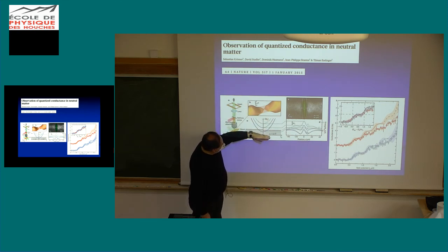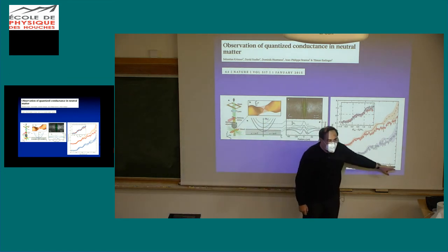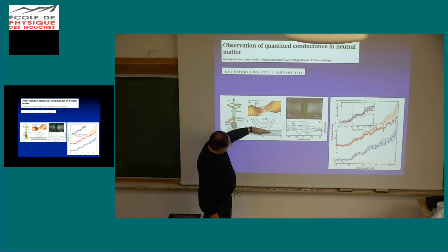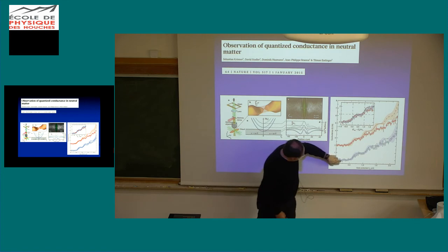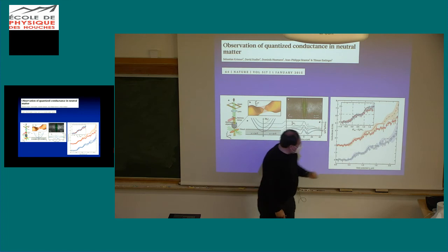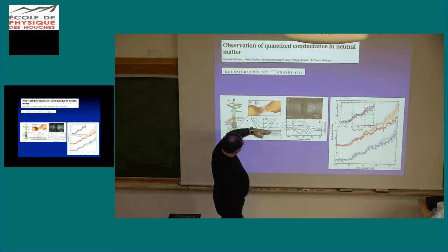And when you change the chemical potential in the channel, which is what they call the gate potential here, initially you have 0 channel of transmission, so conductance is 0. Then you enter a place where you get a good transmission through this channel. You get a little wiggle here at the entrance because also of the finite temperature. The dF dE is not a delta function, but is a blurred object. And then you are in this channel of transmission. You get conductance, which is 1.